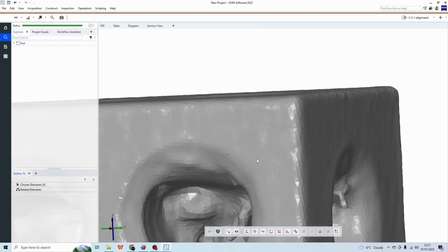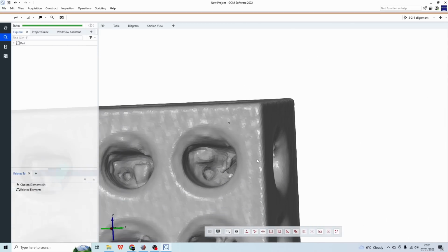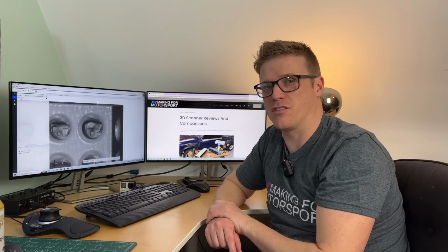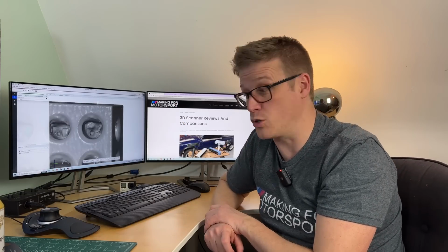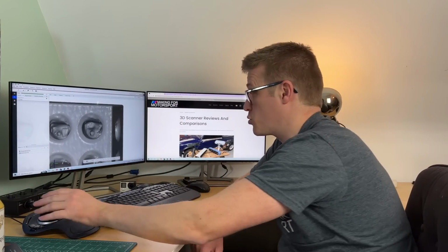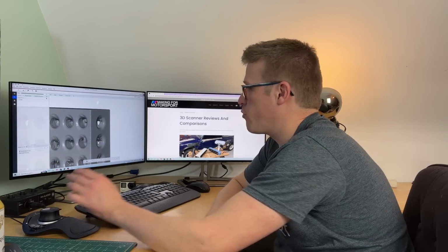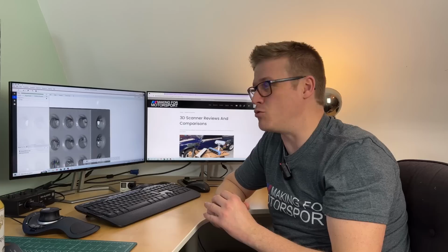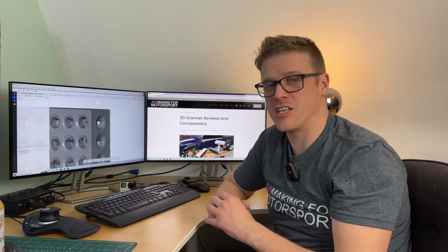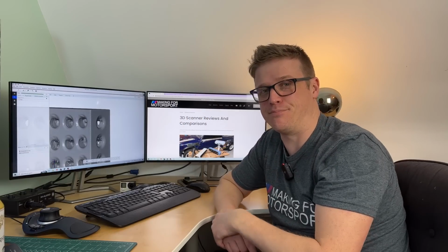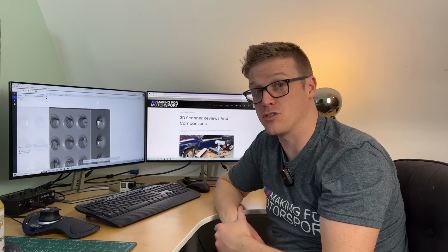It is bumpy. I mean, look at that there. So you can see that is not a particularly great surface to measure from. And all scanners will do that. It's not just the lizard, all scanners will. So what do we need to do first? What this software really lets you do is use statistics to define a true plane on that surface.